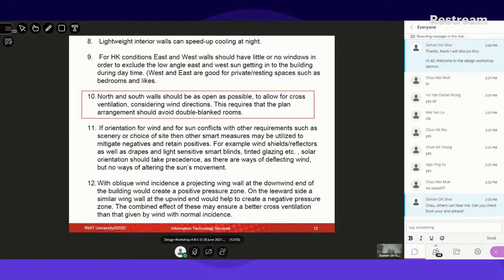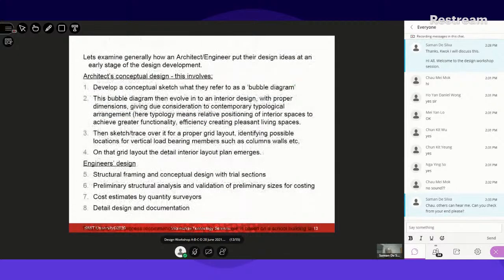So this principle is relatively simple to do, though it is not ideal, by selecting the warmer side to have louvers above, and the shorter, colder side to have the louvers below the windows, openings below the windows. And then these louvers can be adjusted, completely closed and open as well. These are very modern window fixtures coming through as we speak. So in a broader sense, that is how you demonstrate your passive design principles per se.